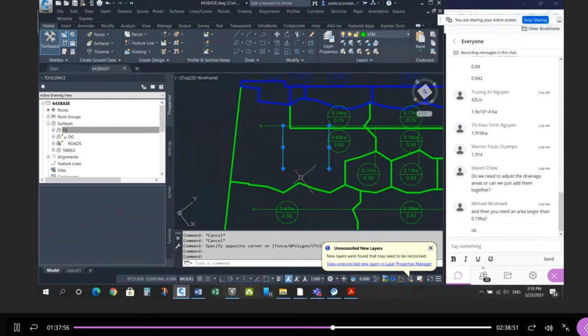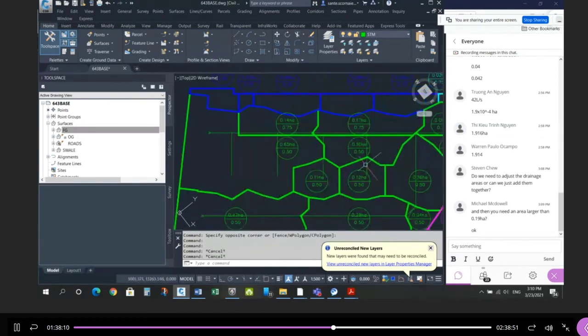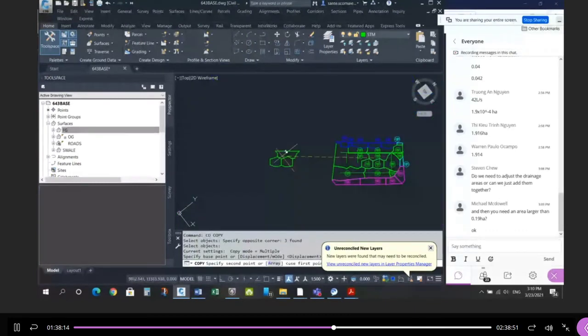Okay, so you need to combine the areas. The backyards that are ultimately going to the same street pipe need to be combined with the area of the street pipe, provided they have the same runoff coefficient. Right? So let me do it one more time. I'm going to make a copy of this. Copy these 3. These should be combined.